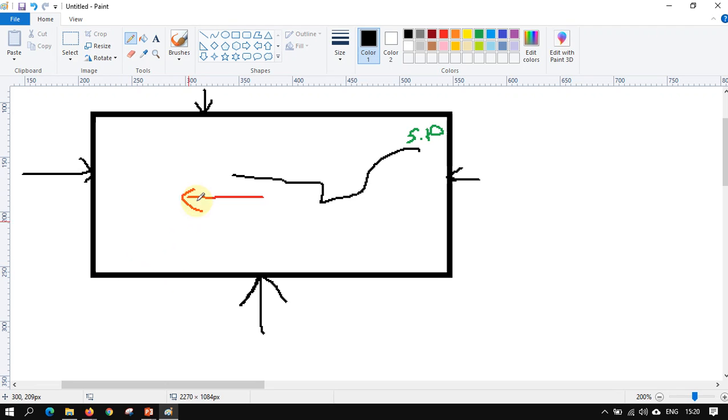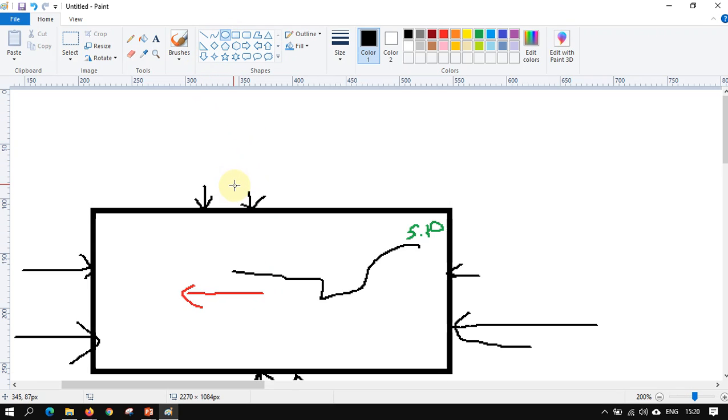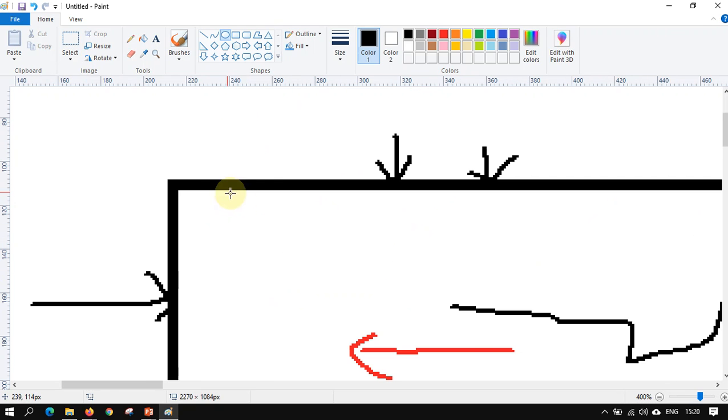There is a force applied over here, over here, and over here. Due to the force applied and the way it is attached, the stress has a tendency to propagate. So what we do is we make a small hole, using a drill over here.